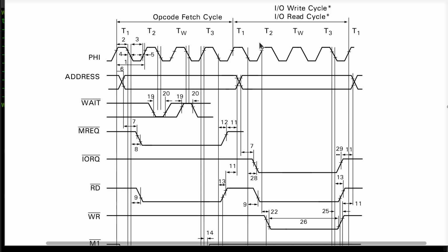Now we have a new problem. We have to make sure that one and only one active going edge will go by during this bus tenure, so that when I read the value, and I reset the status bit that's self-clearing, I don't then try to read it again and see the cleared one, okay? All right. So this is one example of why this is important to do. Sometimes it's important, sometimes it's not, okay?